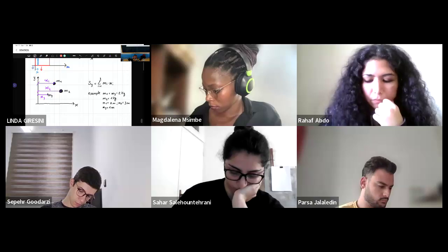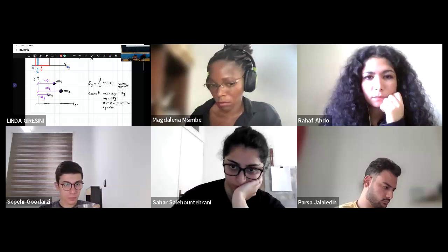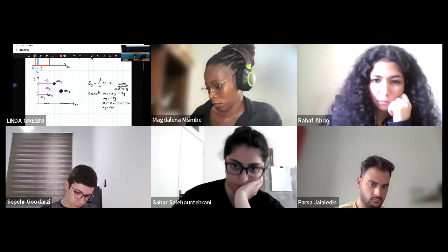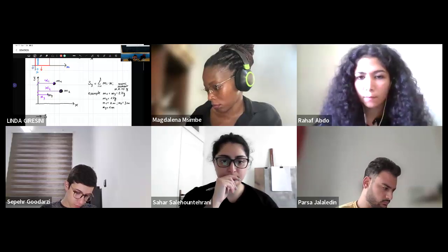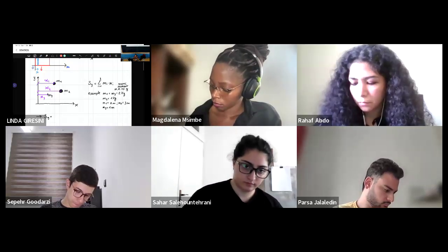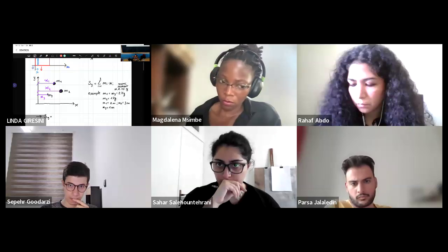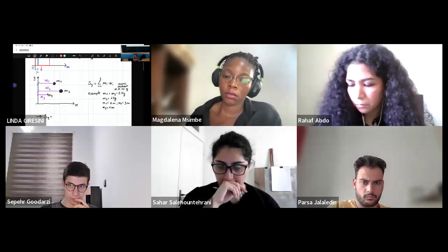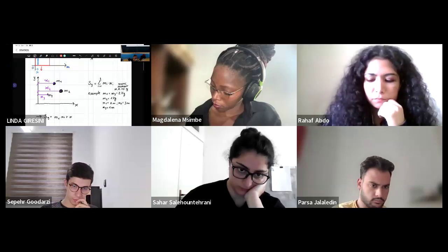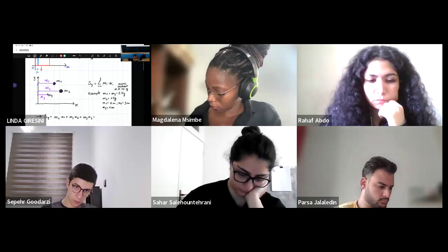So the static moment with respect to the y-axis, by definition, will be the product of each mass times the corresponding distance from that axis, and then you make the sum of these three products. It will be m1 times x1 plus m2 times x2 plus m3 times x3.